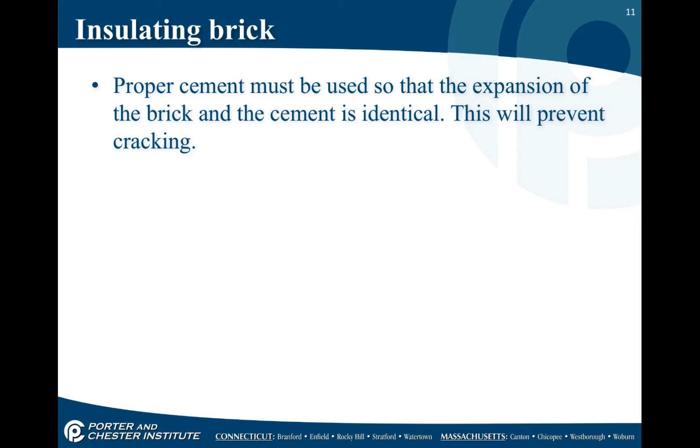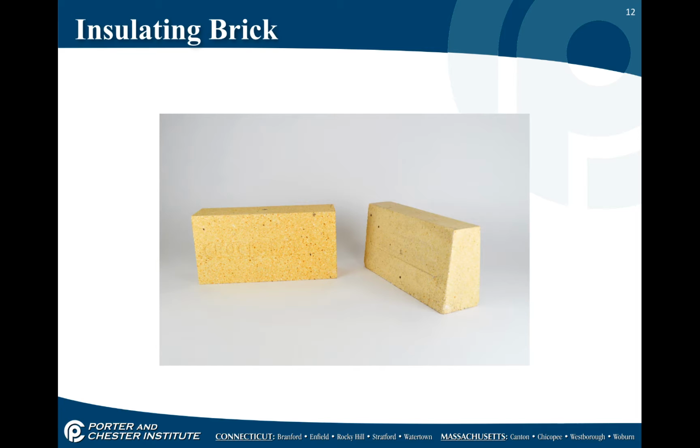Insulating brick, again, comes down to using proper cement. We need the brick and the cement to expand and contract identically in terms of how long it takes. If, let's say, the brick expands faster than the cement, or the cement expands faster than the brick, it's going to start to crack. This is an example of insulating brick. So these would be stacked and cemented together to form the mold of the combustion chamber.